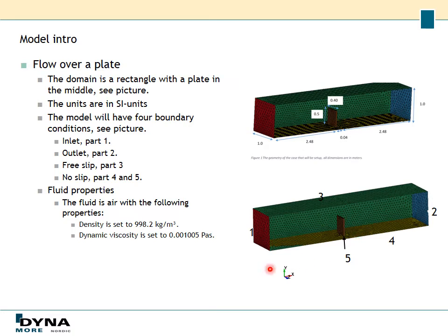And the fluid is set to water with a density of 998.2 kilos per cubic meter and a dynamic viscosity of 0.001005 Pascal seconds.